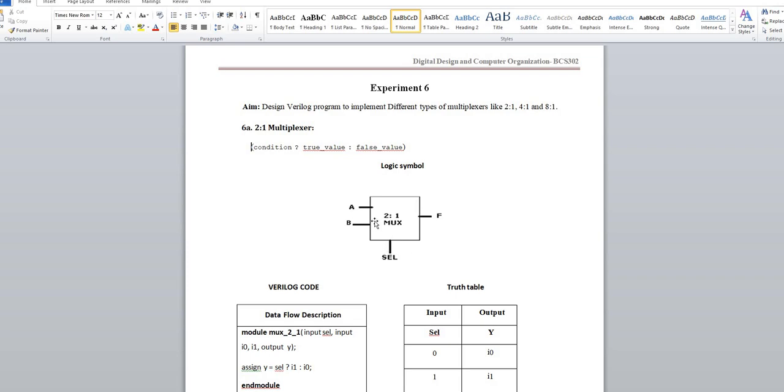This is the logical representation of a multiplexer, wherein with a number of inputs, the output that is selected will be with the help of the select line. In n number of inputs that we have, the select lines will help to decide the input that is to be provided in order to obtain the output. These are combinational circuits built to obey the logic with respect to n inputs and one output. So that is what it says, 2:1.